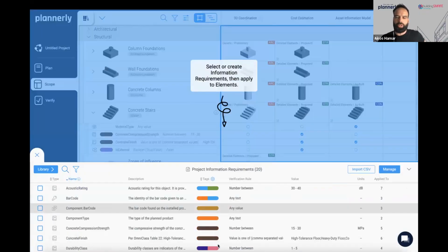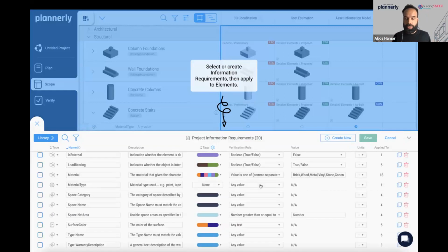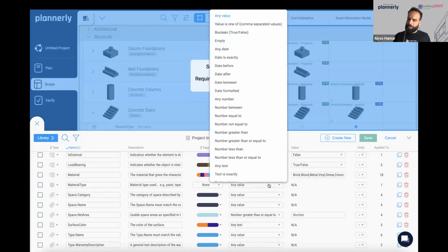Just to spend a little bit more time on this grid. What we see is really first setting up the milestones, which can be, of course, traditional design phases, but we much more think it could be BIM use cases, maybe purposes, why we are creating the model, why we are doing BIM on a project. And in this grid of milestones and tasks to be carried out, we can differentiate and define how certain elements have to be developed from a geometrical perspective, but also who is responsible for them at a given point in time, and what the information requirements added are, and how they develop, and if there is a kind of data drop or how we pass on responsibilities, all can be communicated in a very easy to understand way.